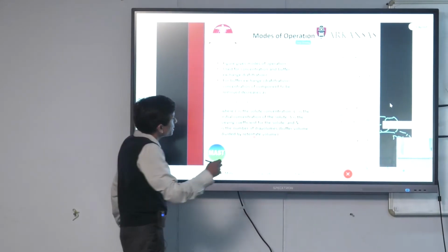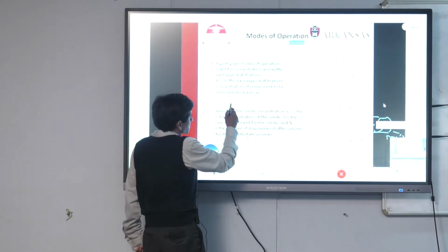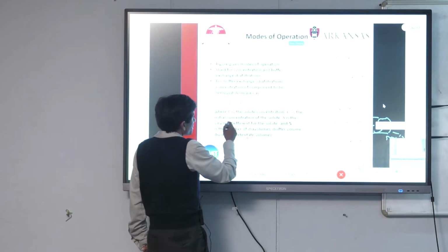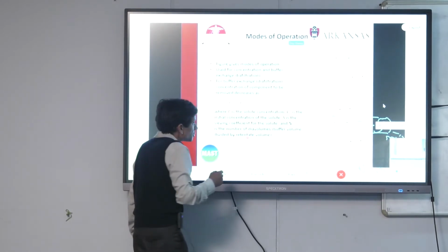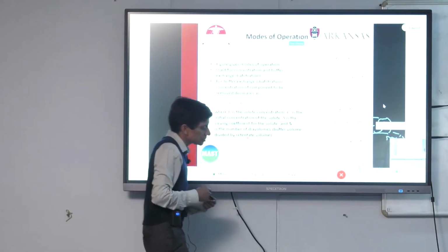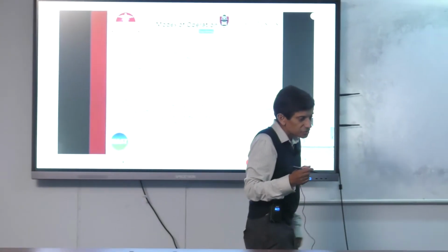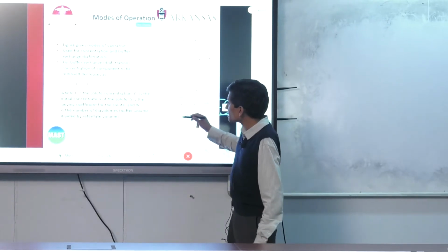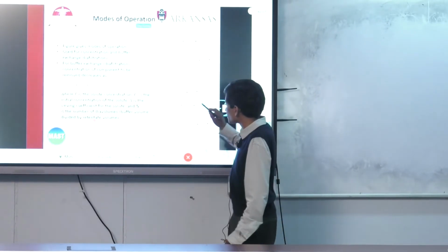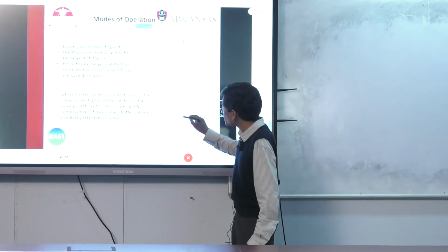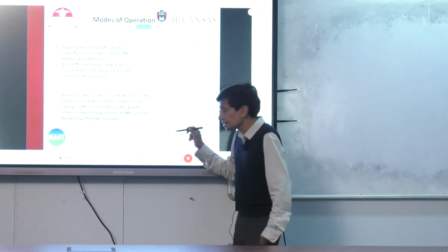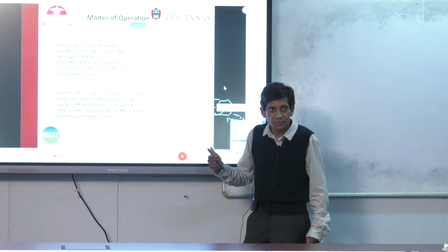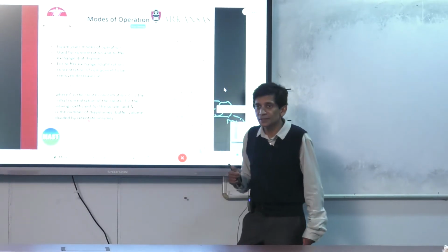So actually, it decreases. C is the concentration of the solute, C naught is the initial concentration of the solute, S is the sieving coefficient of the solute, N is the number of diavolumes. A diavolume is a volume of the retentate here. It's the buffer volume divided by retentate volume. One diavolume: supposing I have 3 liters of feed solution I want to treat, then one diavolume is 3 liters. So it's the volume of your feed.